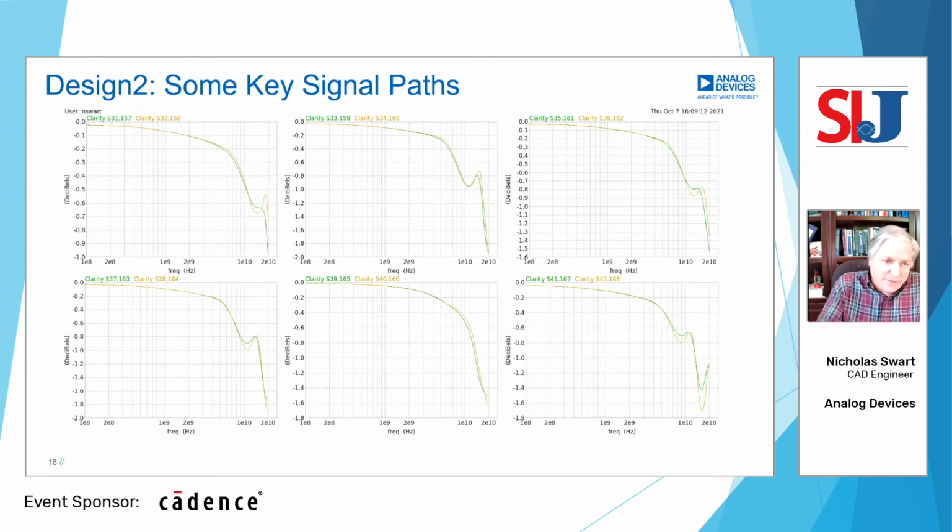And so you would expect for each pair of these S-parameters that they would sit on top of each other, and indeed they do. So it's one way to get at least some idea of how the tool is performing. These also look correct based on what these signal paths are. So this was an expected and correct result based on our understanding of these signal paths and other more dedicated simulations that we've done of those signal paths.